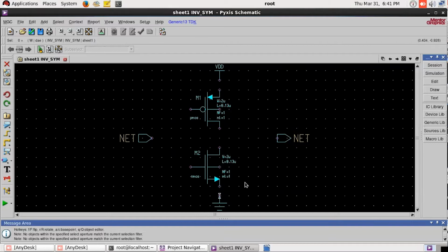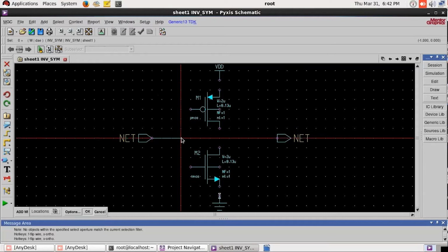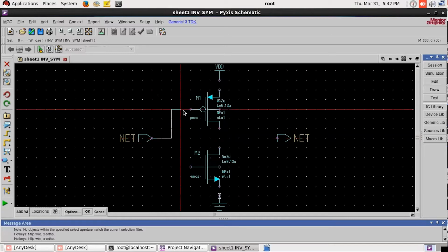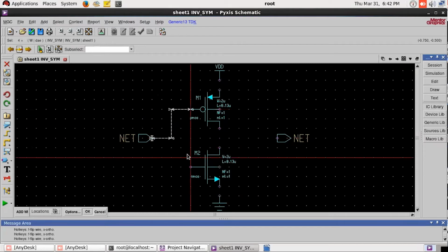Now you have to connect all these components by using wires. So now see here, one wire button is already available. So see, this is the add wire button option. Otherwise you can use the shortcut key W. I'm pressing W here. So press W and click here first. Here I have clicked only once. Wherever the turning is required, click here and click here, and at the place of the end you have to double click. So see here, it's very simple.